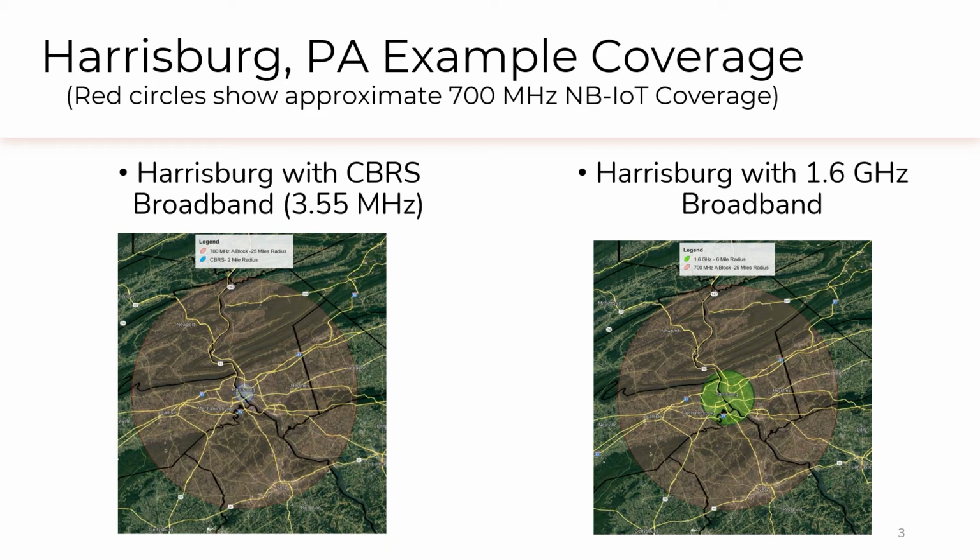Some people would say up to 3, depending upon the specifics of the link and how much throughput you're trying to get. But broadband service, 10 megahertz is what the CBRS channels are, over about a 2-mile range. There are some power limits that make CBRS more limited than some of the other mid-band frequencies that are available. So good for a relatively small area.